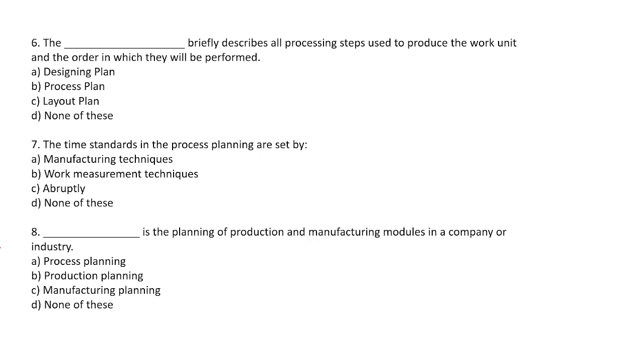Digit 3 interprets internal shapes and features, which may be solid, bore, straight, or stepped in diameter, threads, grooves. Digit 4 is surface plane machining, such as internal or external curved surface, slots, splines.